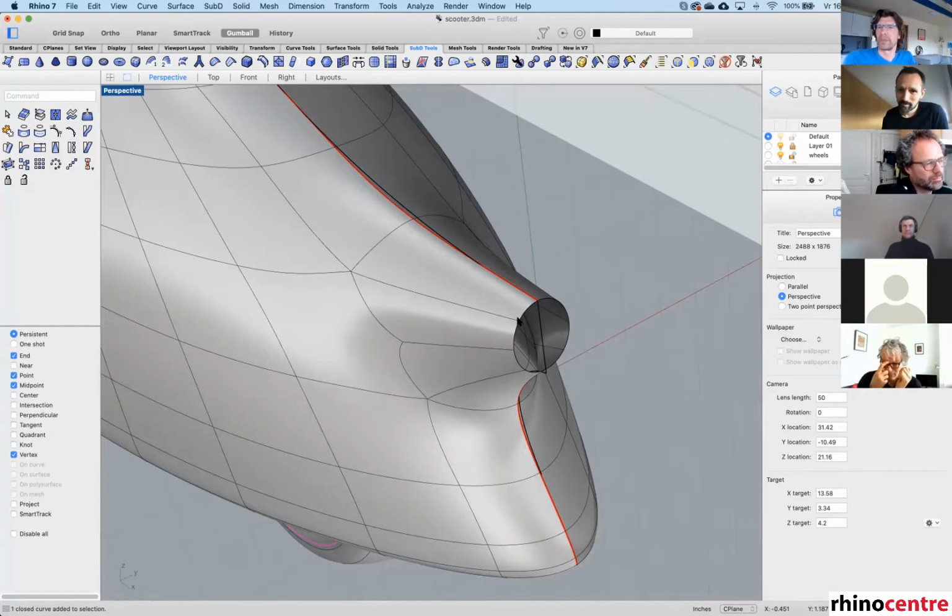No, not yet. The big thing is that for me the loft is just a starting point before I add the details. So if I just convert a NURBS surface to SubD and then add the local detail, for example for the half bulb or the twin stack arrangement, it's not so important how I get to that starting point, but from the starting point, how I do the details.